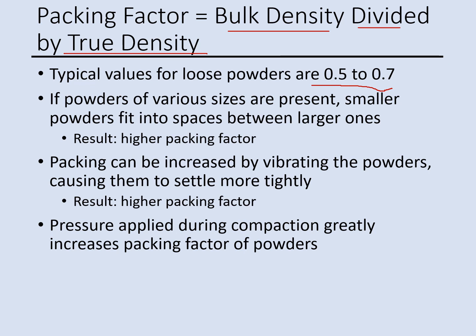And if you have various sizes in the part, for example, some smaller powder with larger powder, what happens is that the smaller powder can fit into the spaces between the larger ones. So this can increase your packing factor.